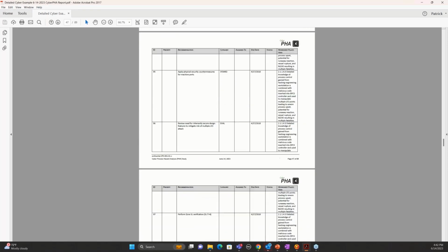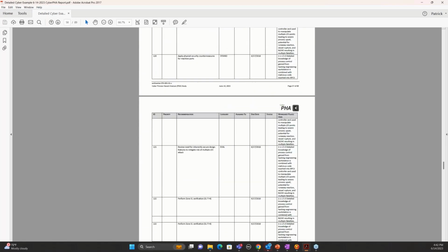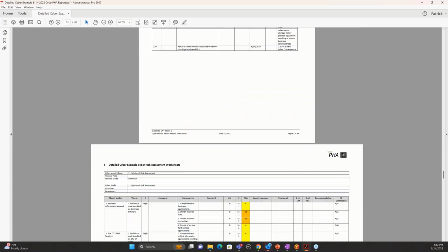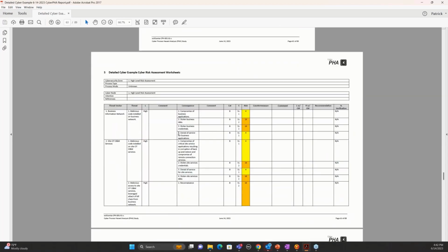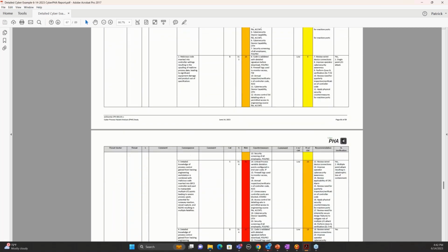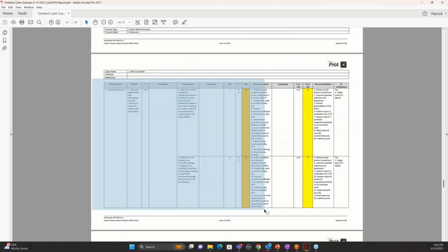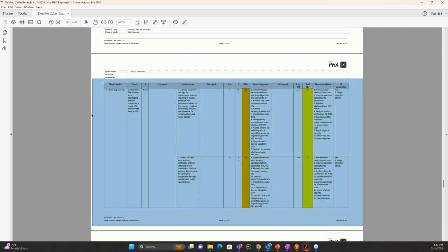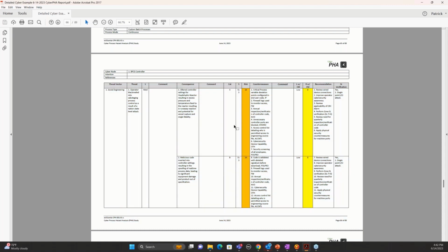And then we also include the full worksheet exports for exSILentia for both the high-level risk assessment, where we're really focusing on just the initial risk, assuming that likelihood of 1 and the worst-case consequence, as well as the full detailed risk assessment worksheet, where we can track everything through from the threat vector, the specific threat scenario considered, the consequence, and the specific countermeasures or protection for reducing the likelihood of that attack.